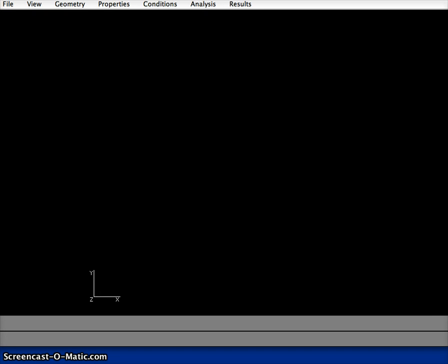In the last video, I showed you how to build a little vertical cantilever model in the Mastan software and analyze it under a lateral wind load, and we saw that that gave us a bending moment diagram that was much like the shape of the Eiffel Tower. In this video demo, I'm going to show you how to get some insight into the behavior of arches. I have Mastan open, again with a blank modeling window here, and I'm going to start by defining geometry.